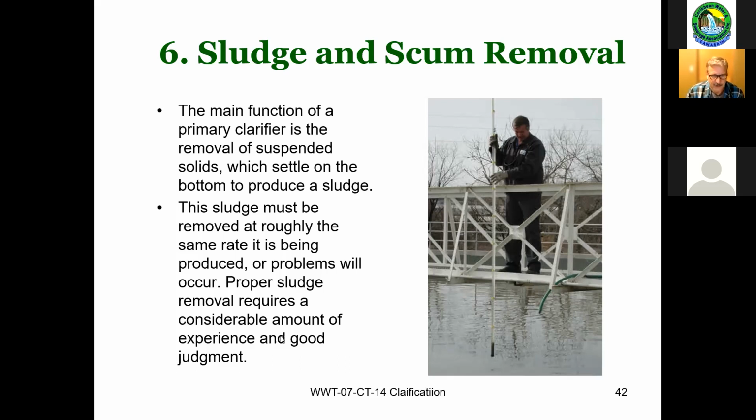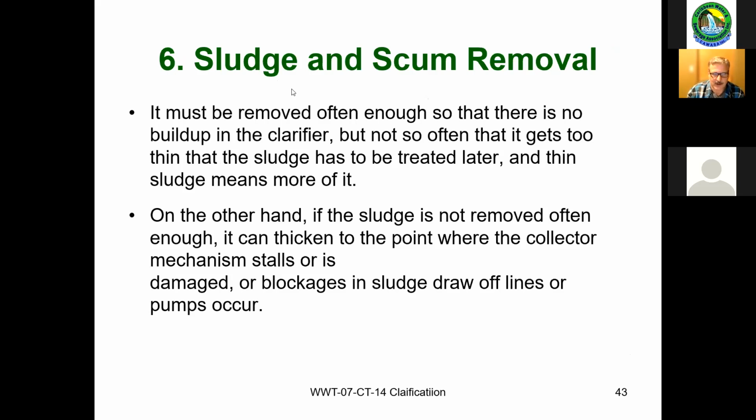And following that, you're going to have enough sludge built up that it's going to cause you problems in your primary clarifiers, and you could well be breaking shear pins, which would typically be the first thing to go between the drive and the chain. That's the sacrificial piece, letting you know that there's a problem in that clarifier. I have seen locations where the shear pins keep breaking, so they put in larger shear pins, or they'll just throw a bolt in there to keep things going. But people are avoiding the problem or potentially causing more grief by making those systems run when something is dragging.